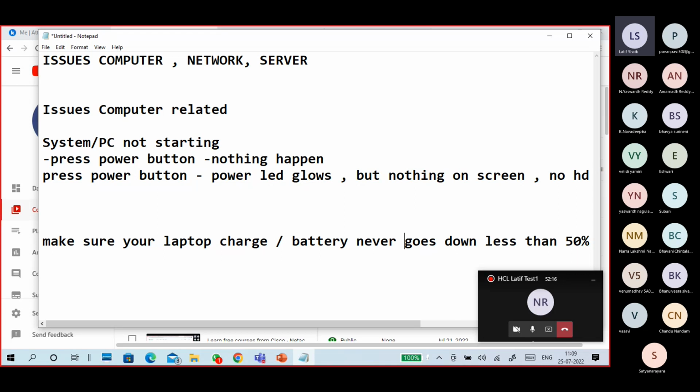Again, people think the battery should be run dry, meaning charge it to 100% and keep working until it goes down to 10%, 5%, 0%. If it is completely dry, then put it on charge, and it will give you more battery. No, guys, that is completely wrong. I hope you understand. Okay, you put a charging.